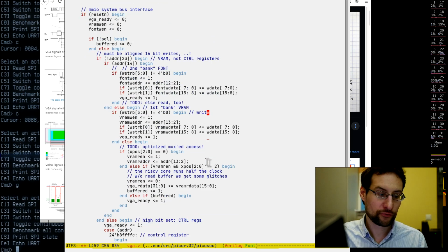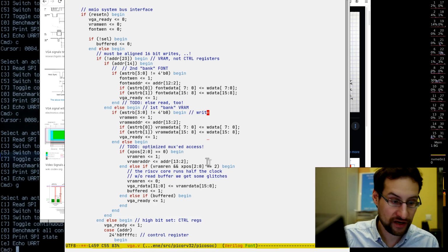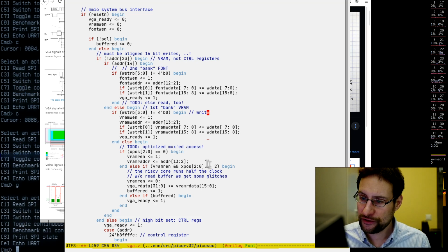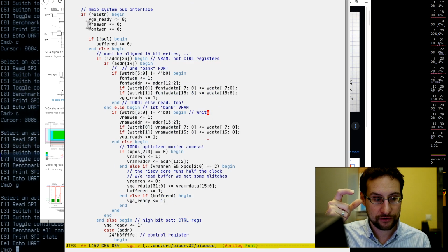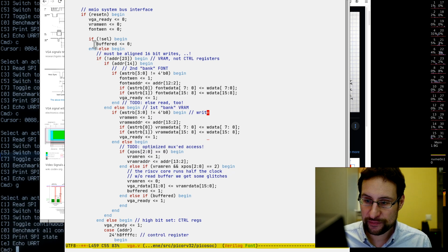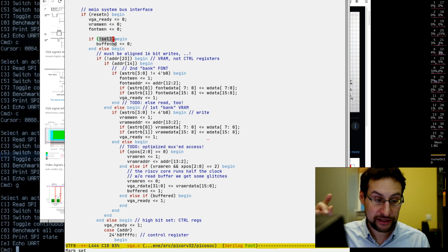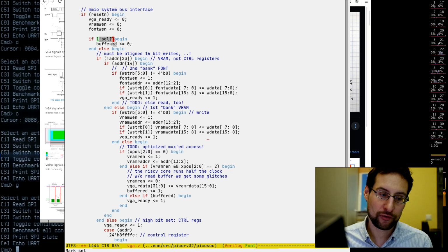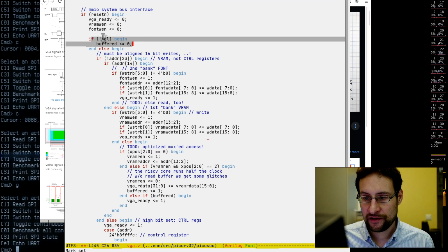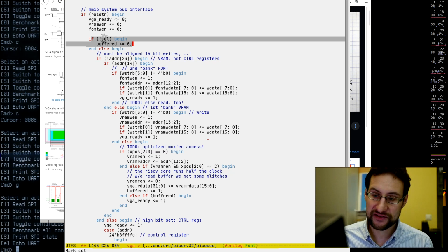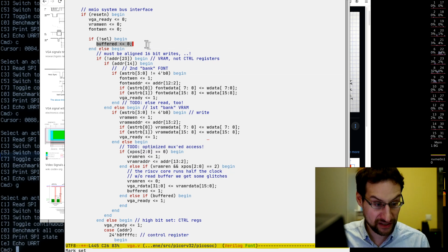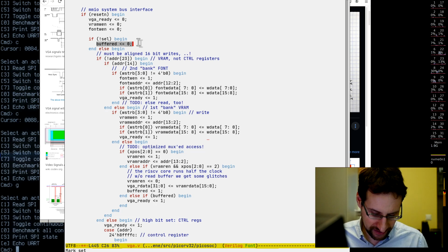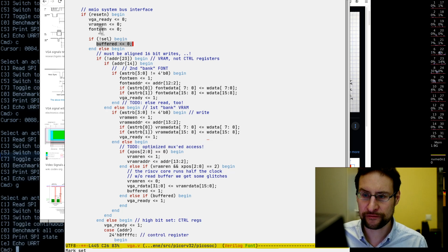So we are mostly through with this super fast run through our Verilog video core stuff. This is a memory mapped I/O interface with our PicoSoC RISC-V. Also a little bit tricky. This is a select whether we are chip selected as in our video part here. If not selected, then reset some buffered. This is our buffered read register that I needed to optimize the memory transfer. It actually was super tricky. That took me nearly an afternoon to get working stable, because of double buffering and memory timing glitches.